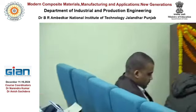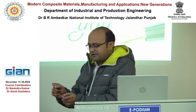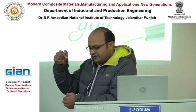Yeah, you can use it with thermoplastic resin in the case of commingling. But again, there is a limitation of commingling. For some fibers that are brittle in nature, again you will get a problem. Like carbon or glass, it's very difficult because the commingling is done by air. During that, the air flows at something like 45 degrees, so it will crack and fracture the fibers during the commingling process. That may create defects.